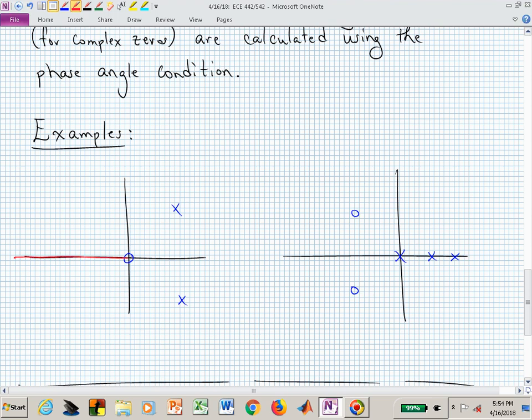What rule 5 tells us is the angle with which we depart those poles. And the departure angle is measured with respect to this real line segment going off in the positive direction from that pole. And that would be our alpha sub d. So if that was in fact the departure angle, then we would be doing this. As we cranked up the gain k, we would leave that pole at that angle, alpha sub d.